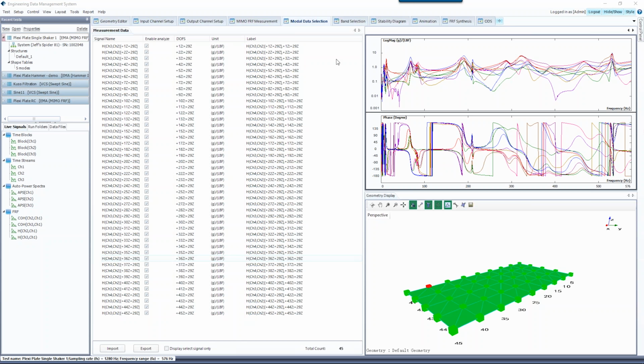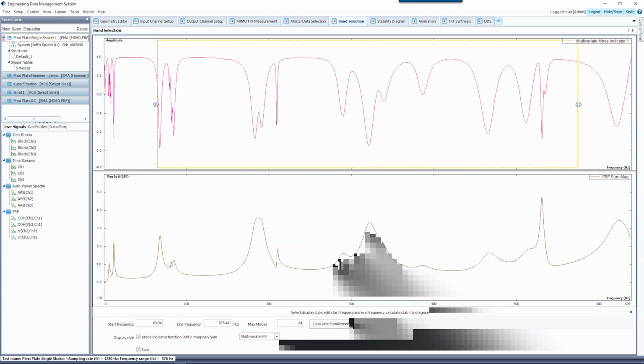And also you can change the format. You can check magnitude phase or log mag phase, or you can check real imaginary. And many times the imaginary part, if you are measuring acceleration versus driving force, you can look at the imaginary part, whose peaks indicate kind of like the mode shapes. If you have a simple beam, you can just imagine how the mode shape is going to be. And all the supported features are there.